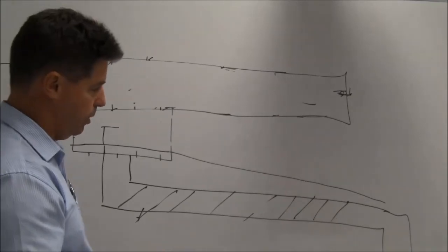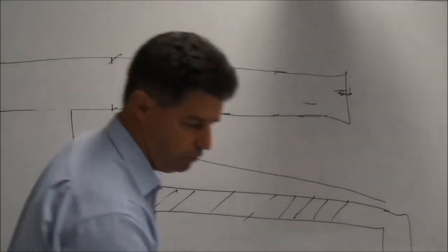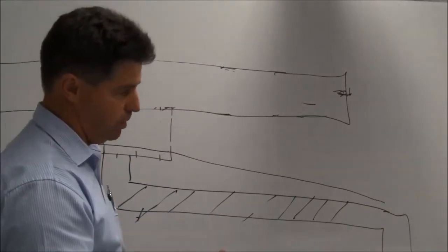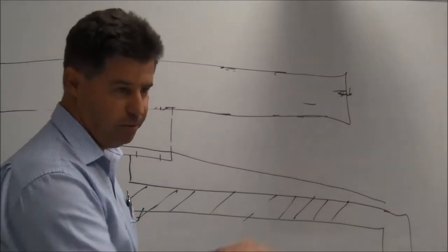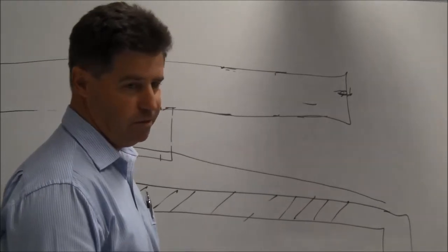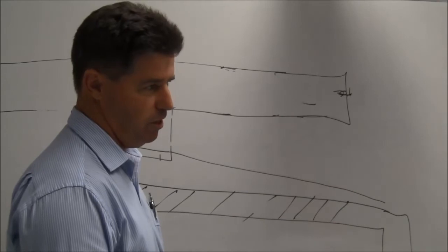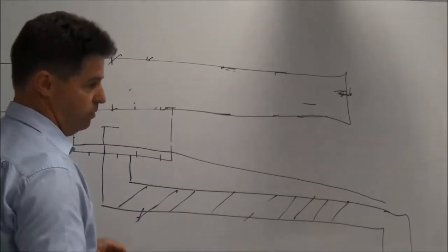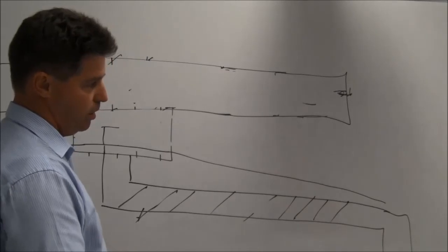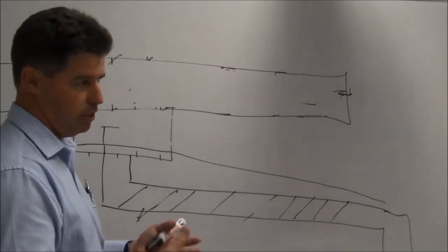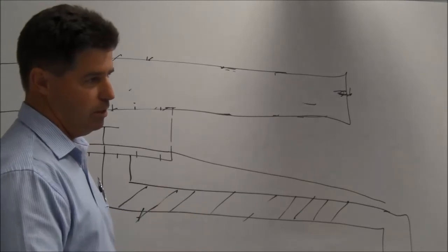The best way to explain friction, which I do with the guys at work, is if you put your finger on the table and rip it across the table real quick, you burn your finger. So obviously there's a lot of friction because you're doing it fast. If there's a lot of velocity in the water, the flow rate's quite high, so there's more friction. The bigger the pipe, the less friction, and hence why we increase pipe sizes.